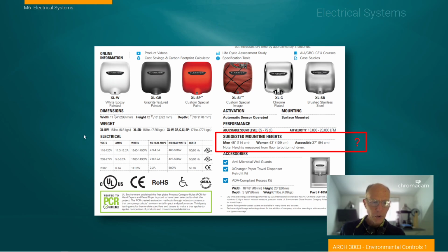The important thing about electricity here is that you should be able to look at a chart like this one for electrical supply, understand the voltages that are being stated and what their implications are for planning and specifying on your drawings, how much amps it requires, what that means as far as significance, and maybe some of the things that aren't necessarily important, like once you supply these, this tells you how much energy is required to consume, so you can tell if one's more efficient by the amount of wattage, but it isn't a requirement to necessarily be on a drawing.